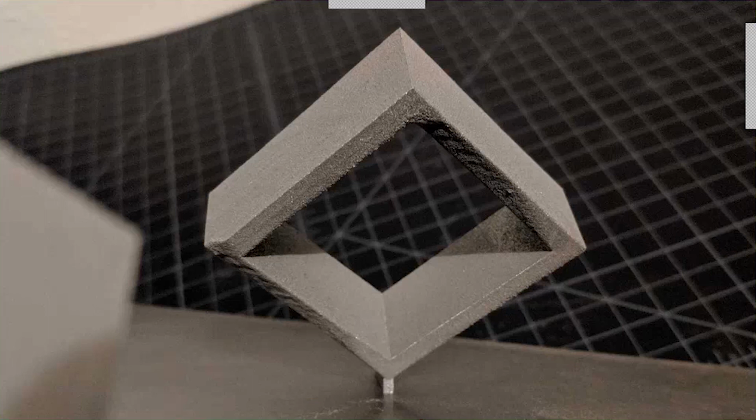And this is really an interesting case because we have one half of it that built great, and we have one half of it that kind of had some build issues. So this is actually where we're right on the edge of whether we think it's going to fail or not. And it actually comes down to the ability of the machine and process to compensate and just the robustness of this printing process to account for some of those. So the ones that are undercut were perpendicular to the coater direction, so they're parallel to the blade, and that did some odd things with sweeping powder onto it, sweeping powder off of it,